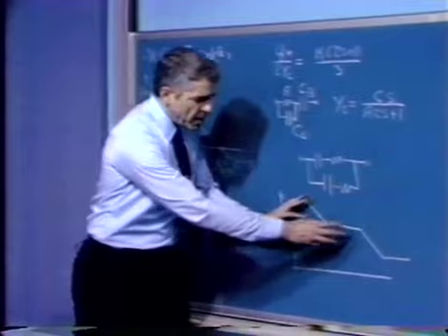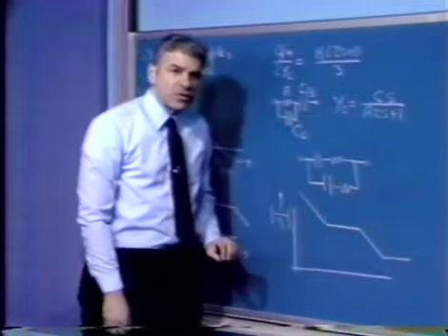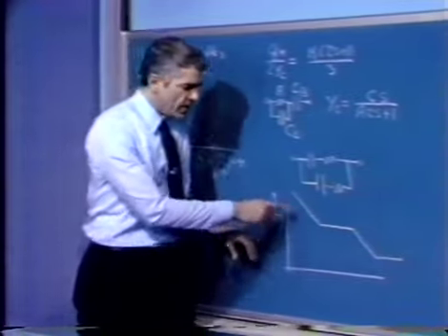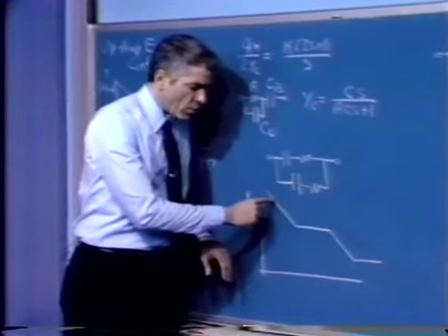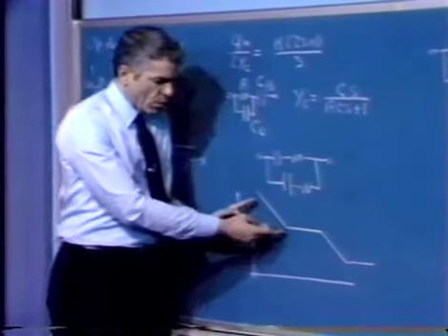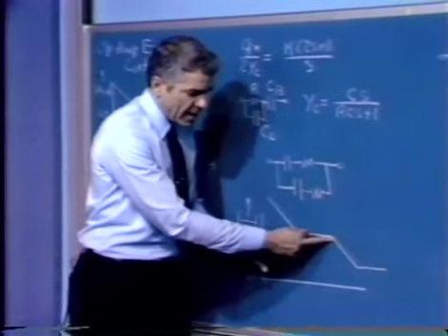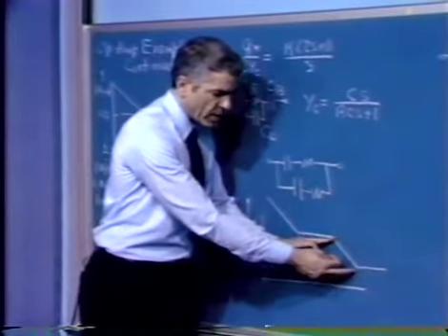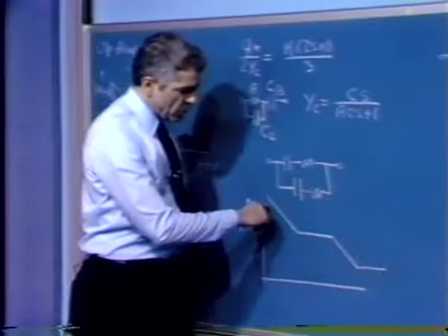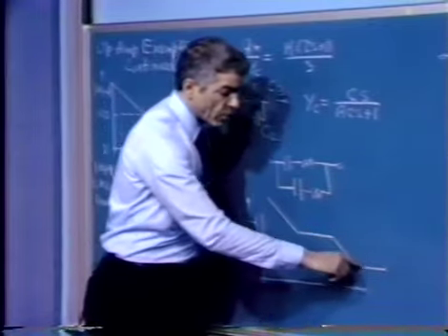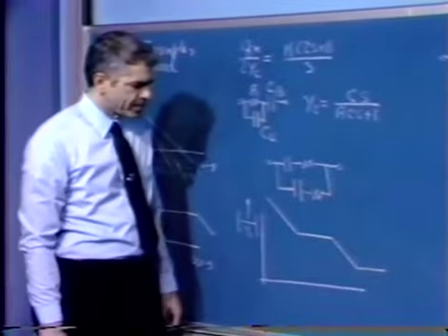And if we space the poles and the zeros associated with this transfer function closely enough, we begin to approximate a 1 over radical s roll-off. We'd roll off as 1 over s half the time on logarithmic coordinates, be flat half the time, and so forth, and begin to approximate a 1 over radical s roll-off.